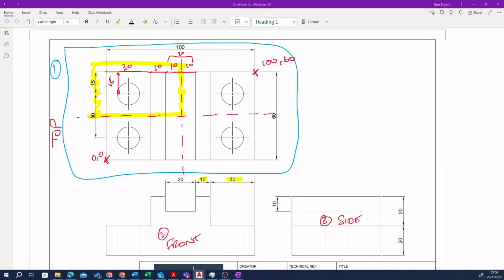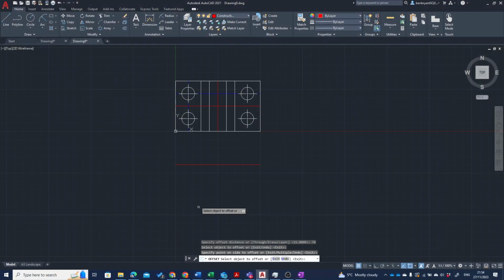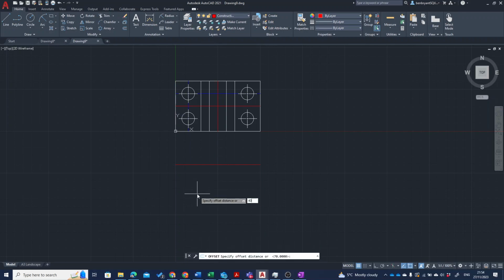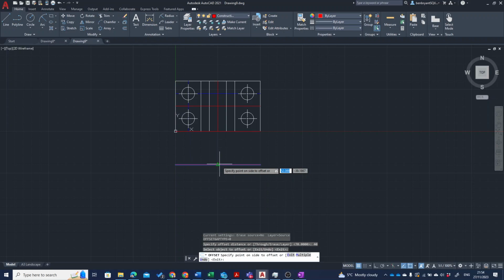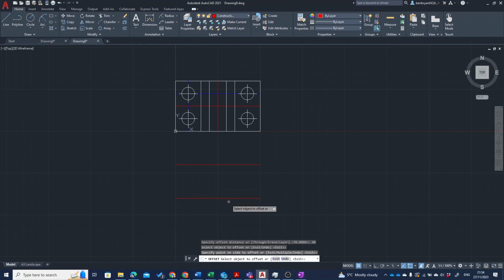So when I go back to the drawing, the height here is going to be 20, and a 20 to 40. So escape, space, 40. Drop that one down again. That's given me the front view of my shape.